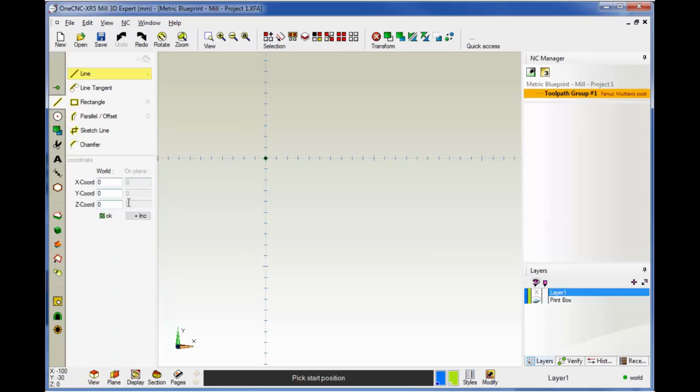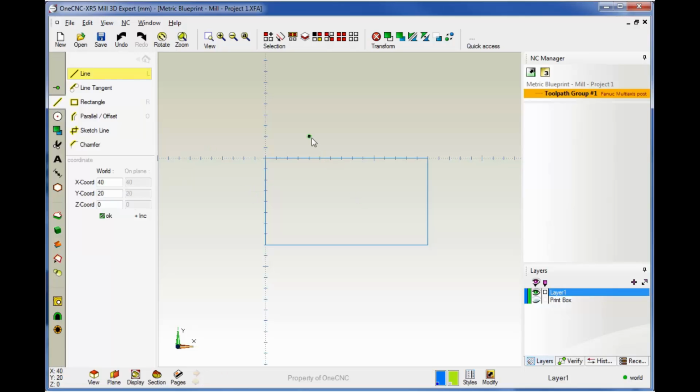All right. Now, before I use coordinate input, I want to point out that you can grid snap if you'd like. We could come over here and snap the datum. I could come over to X of 150 and left click down to a value over here to X0, back up to the datum, and when I'm finished, I can right-hand mouse click. All right, so if you'd like to do that, by all means you can. I believe for a system setup in metric, the grid snap units are 10 millimeters.